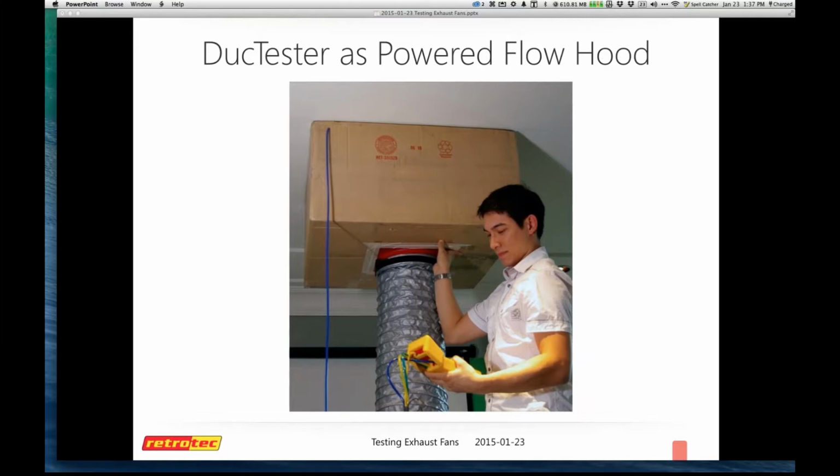If you do have a DM32, we highly recommend that you always check your firmware updates. Right now we're on version 49. When you first turn on your unit, at the bottom it'll tell you what firmware you're on. If it does not say 49, connect it to your configurator. You can go to the settings and toggle through all the pages, and on the back page it tells you your firmware. One of the last changes in the firmware was that the window at the top says blower door, and it shows the image of a DucTester without the actual flex duct on it, described as a 300 to be used as a blower door.